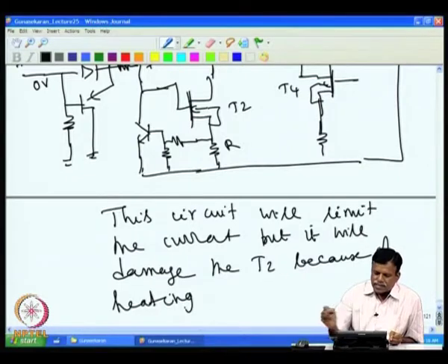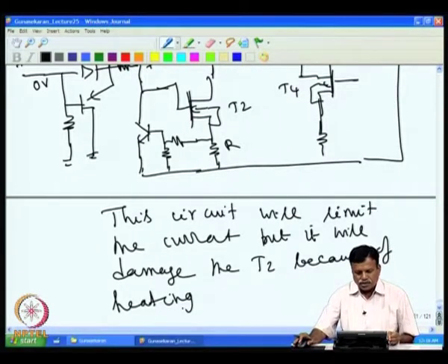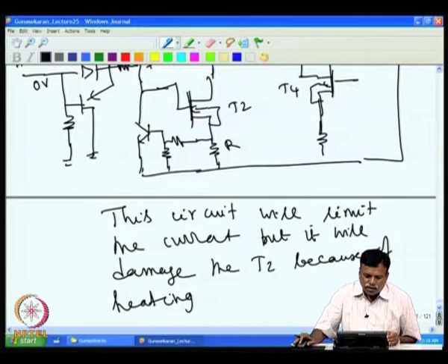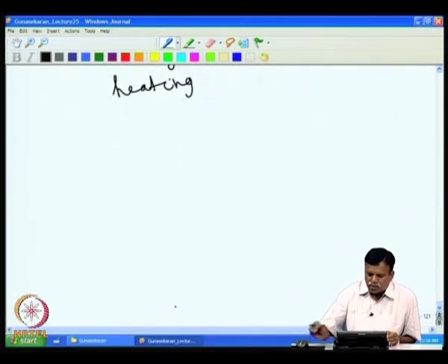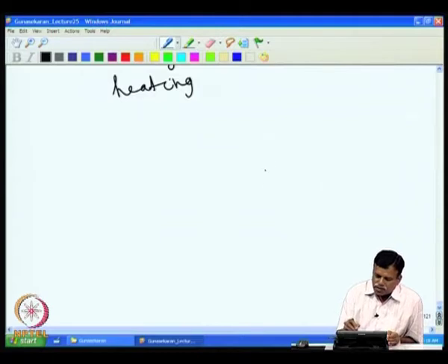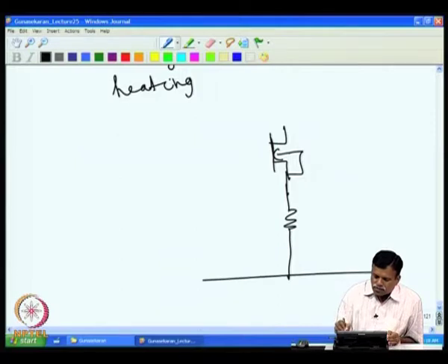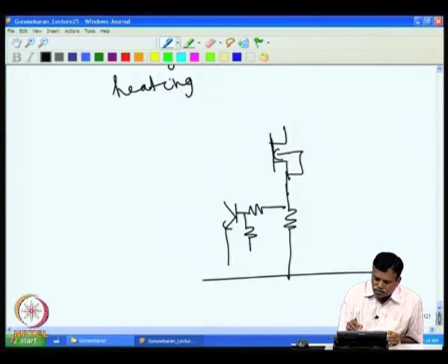So, we had to latch the pulse. So, that is to be done. So, we can add a latching circuit to the above. So, what we can do is I redraw this last part alone. So, we have the MOSFET and then we have a sense resistance here. Now, what can be done is that we can have a sense resistance and then that is connected to this.